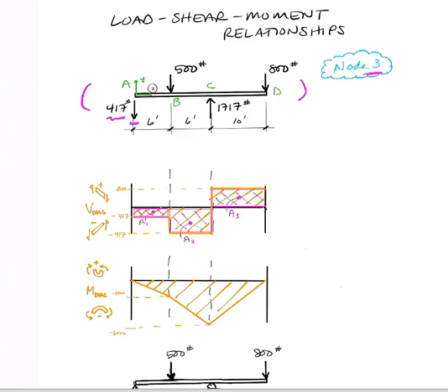Now the fact that that was a support force, the beam really knows no difference between that and an applied load. All we have are loads on the beam, and so that's going to kick my shear diagram down. We will derive that shortly, just on the next page, but a load in the down direction is going to move my shear diagram down.